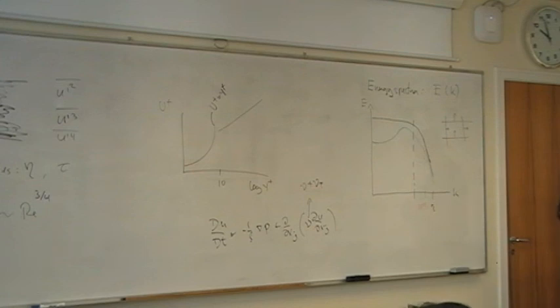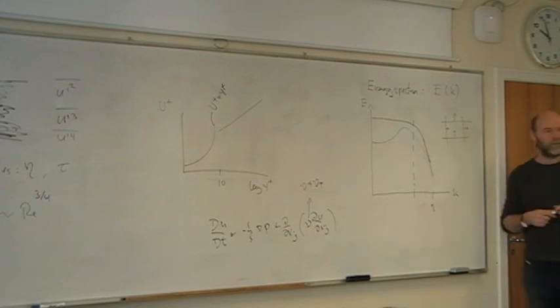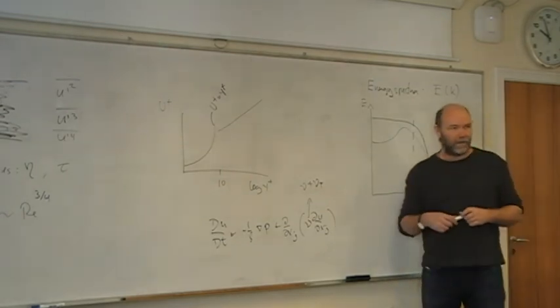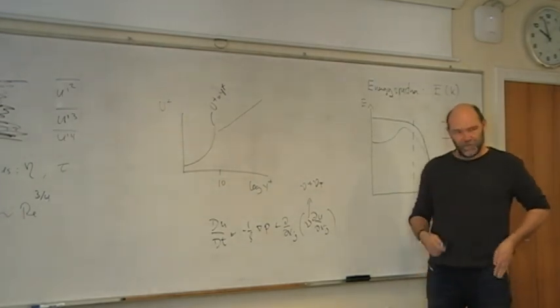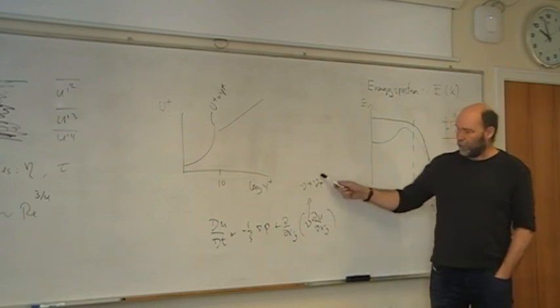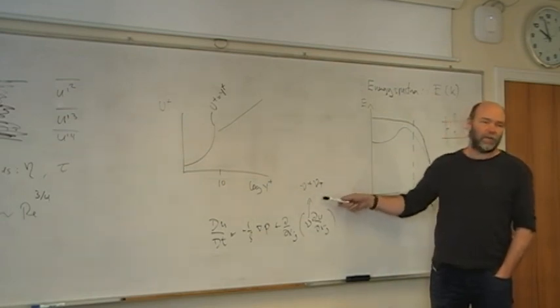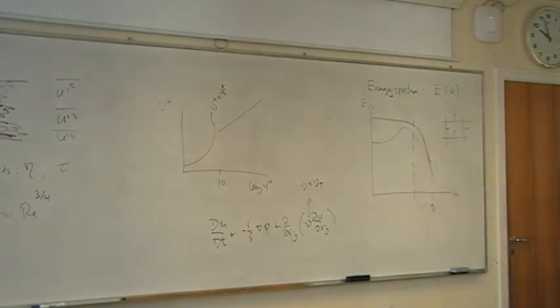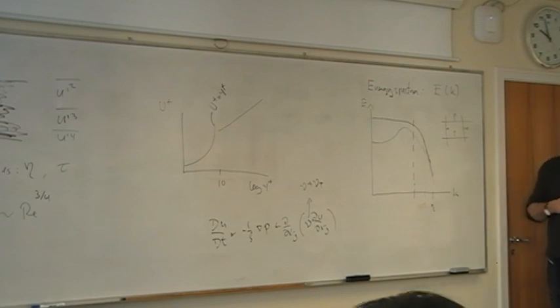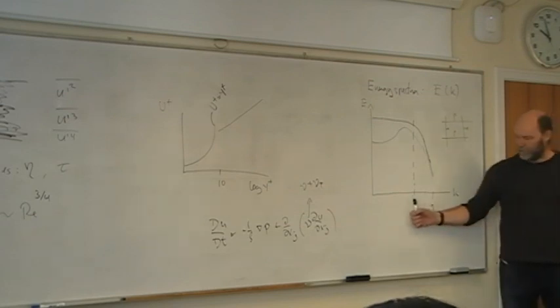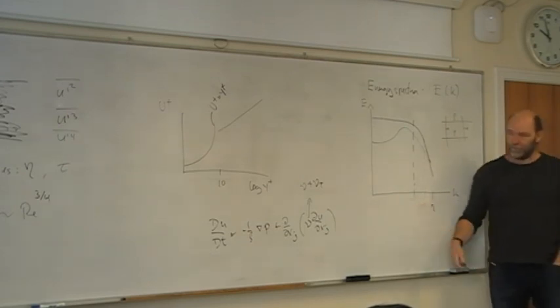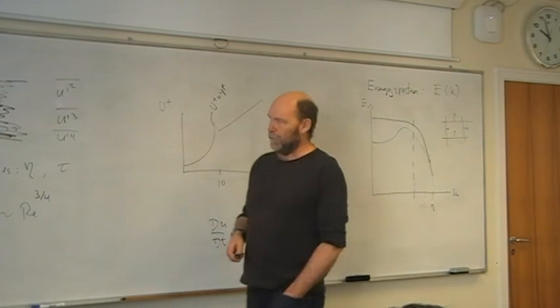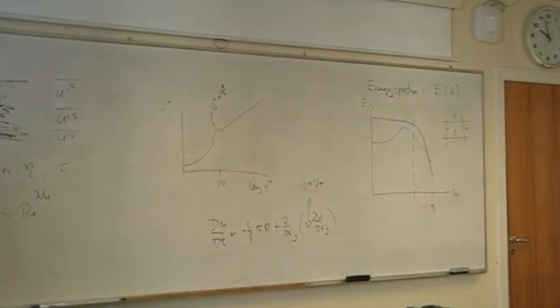And it turned out that he used a third order upwind scheme, which has an additional artificial diffusion, which was acting as a subgrid scale model. So he was actually doing an LES without being aware of it. So LES slash DNS can still produce decent, reasonable results, although you are pushing your limits a little bit too far, the Reynolds number is a little bit too big, and then, even worse I would say, people will also cheat.